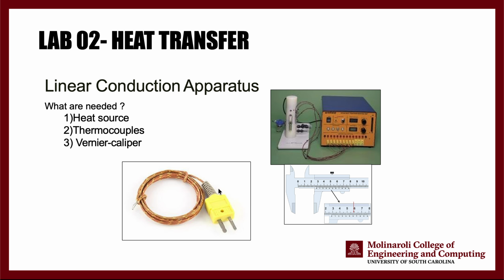And then we have installed thermocouples that look like this at 8 points of the system on the metal that is inside itself. You are going to cool this bottom part of your sample, heat this top part of your sample using this heat supply, and then you have to wait for 20-25 minutes for everything to become steady, and that's when you can do your calculations and record your data.